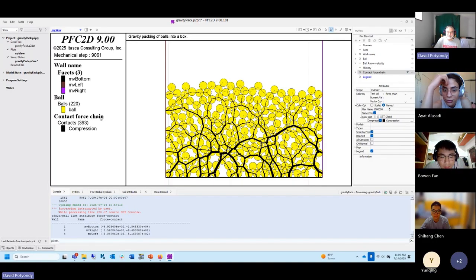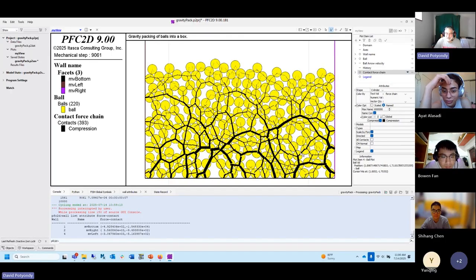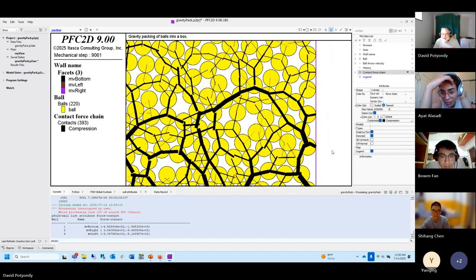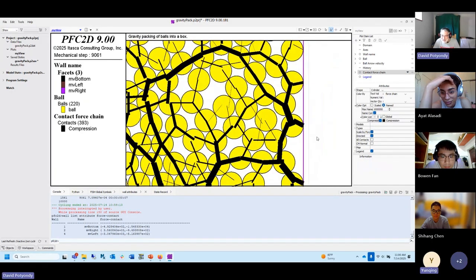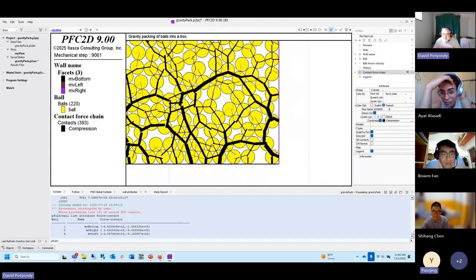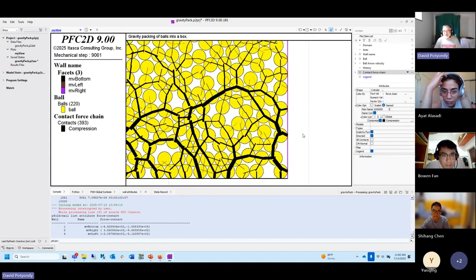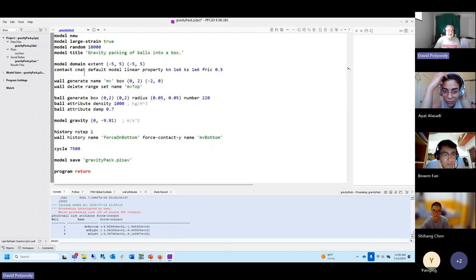Force chains. Okay. Notice they're bigger on the bottom because of the weight above. That makes sense. But look on the sides here. This force is pushing that particle upwards. So is this. So that's where the load's getting shed into the wall. Let's run it again with zero friction, and we're going to see that these force chains should all be perpendicular.